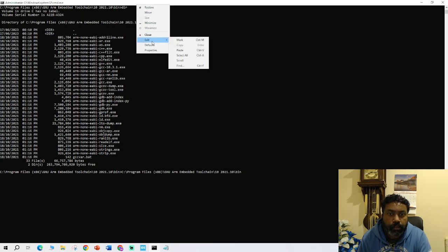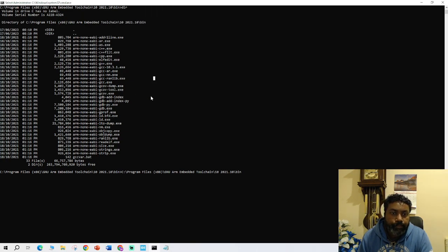I'm going to maximize this, just one sec. I hope you can read it. So these are all the binary executable lists. The one with -gcc.exe, arm-none-eabi-gcc.exe, this is the file that you're going to use for compilation, linking, and assembly. And ld.exe, this is for the linker.